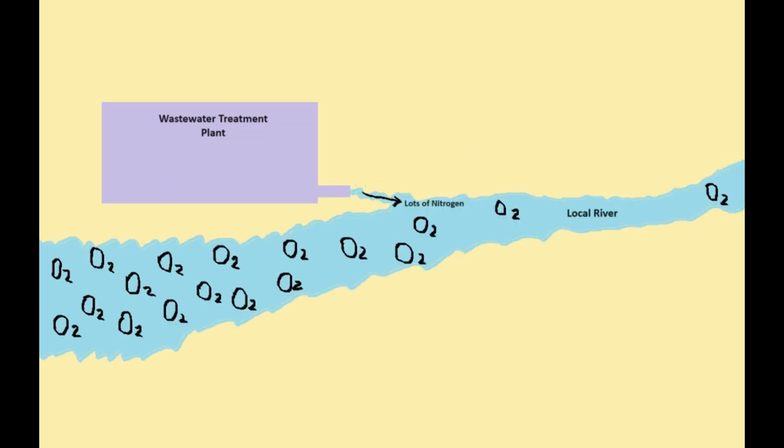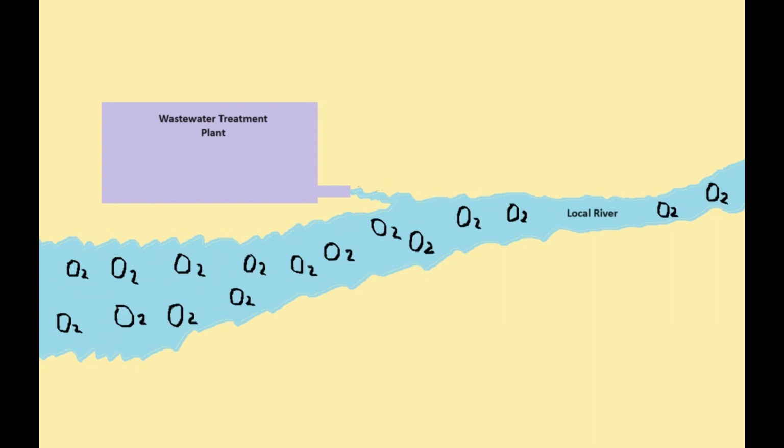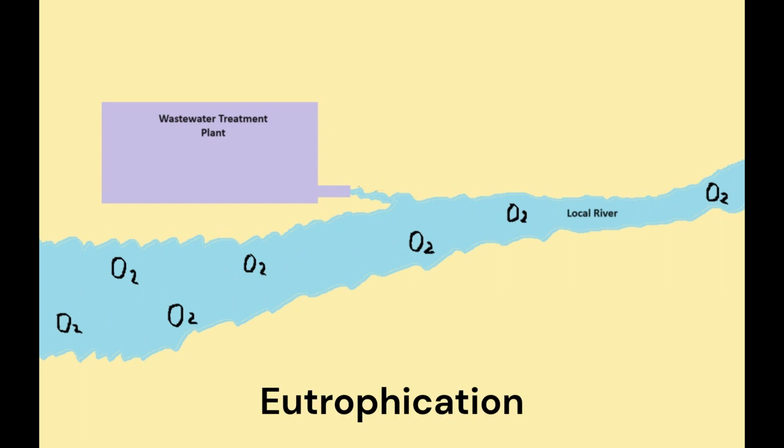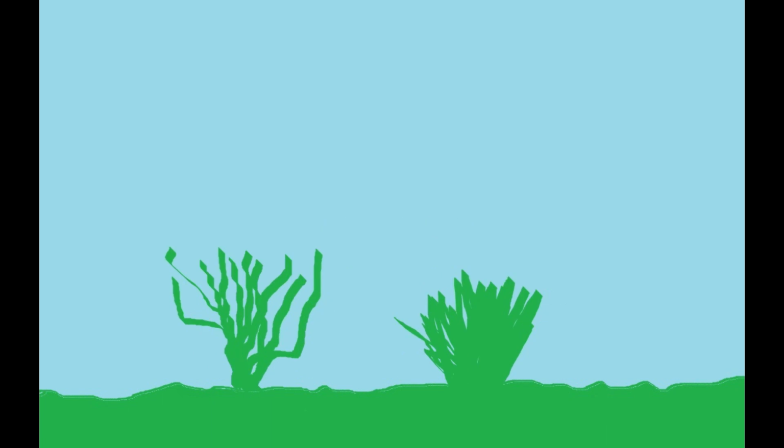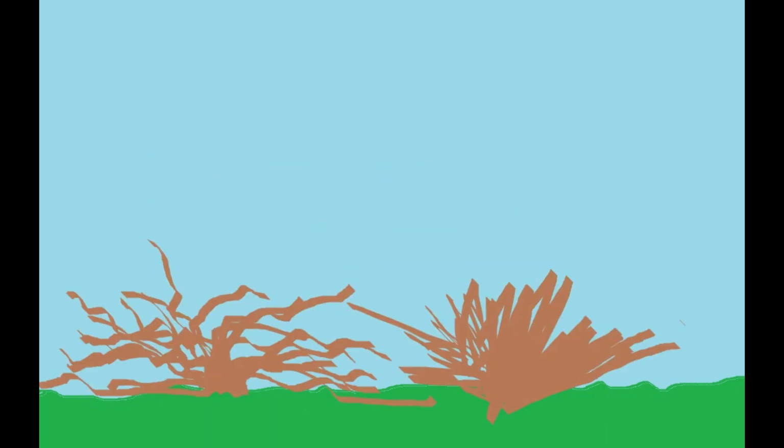Nitrogen, such as in the form of ammonia, has the potential to be extremely harmful and toxic in water. If wastewater that is returned to the environment is high in nitrogen, it will result in the rapid depletion of oxygen in these environmental waters through a process called eutrophication. When there is lots of nitrogen available for aquatic plants to consume as a nutrient source, they begin to grow uncontrollably. When these plants die and begin to decay, the process of their decomposition by aquatic microorganisms is heavily oxygen reliant, which quickly diminishes the oxygen supply available for other aquatic life. Nitrogen concentrated water is also very dangerous for human consumption.